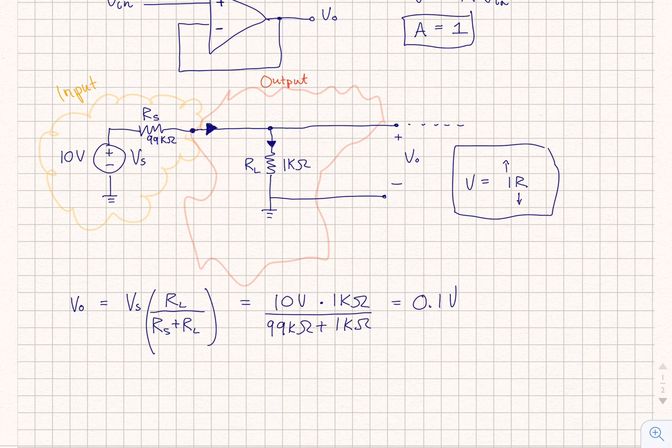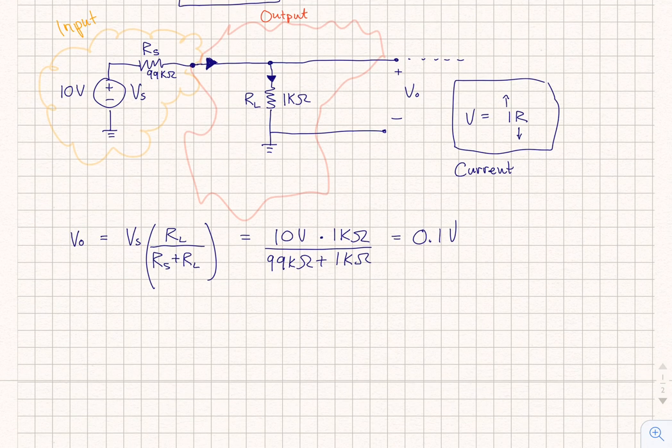Really, it's a current amplifier. You can think of it as a current amplifier, or a current source in a sense. Because if you want to keep VO exactly the same as VS, and these impedances change, then there has to be more current flowing through it. So it's a really cool thing, because between two stages of your circuit, you can boost up the power, because you're boosting up the current, keeping the voltage equal. All right. So you see the problem is just connecting these two together.